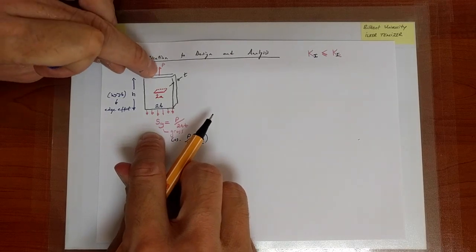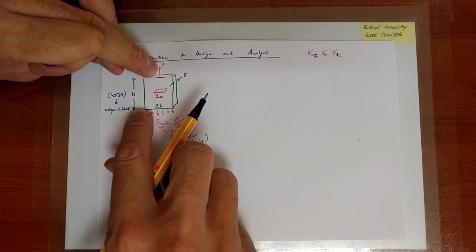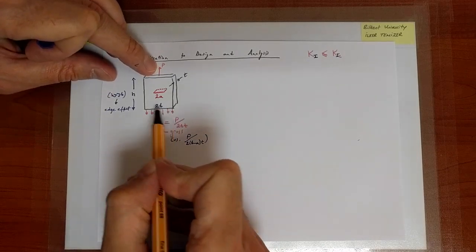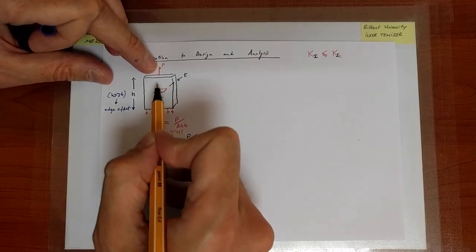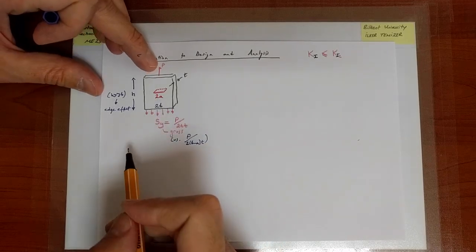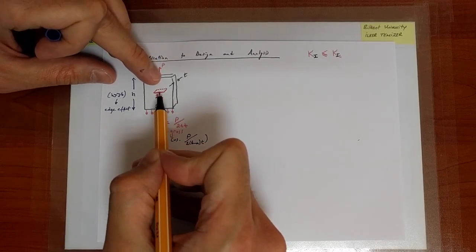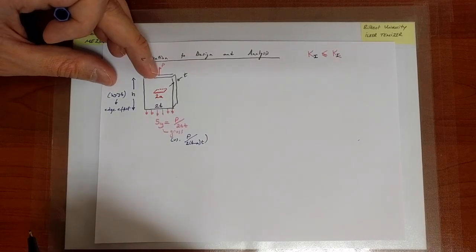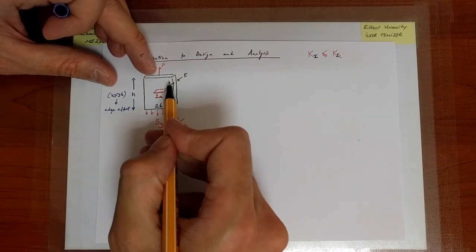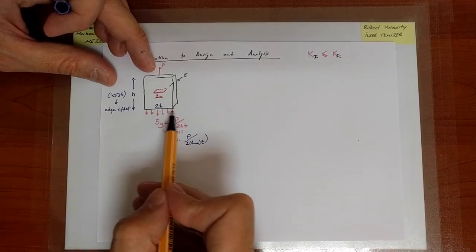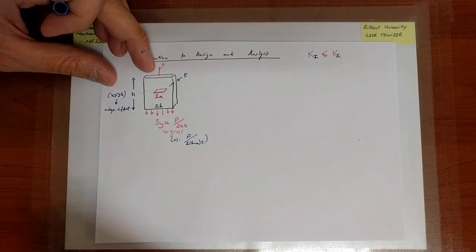So when you actually apply a load of this type, you will never have at any cross section a very uniform stress distribution in that direction, normal stress, because you can never be sufficiently far away from the crack location. Every point throughout the plate will feel the presence of that crack. Okay, but presently that's what we are going to assume, and for sure sufficiently far from the crack, the stress will be uniform and looks like that.